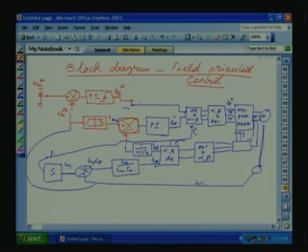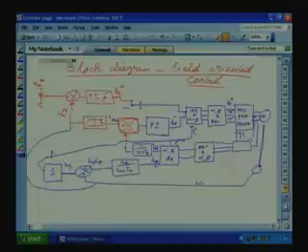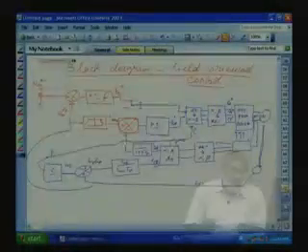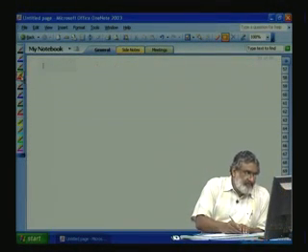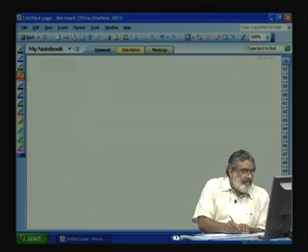Before the actual implementation is done. So this is the current hysteresis controller. Now if you want to use voltage control, how can it be done? See, we got the field oriented control now. Now how do you design your controller? For the separately excited DC machine, we have found a set of rules to find the PI controller. So let us draw the closed loop schematic. The same techniques we use for the separately excited DC motor, we can use here also. So let us see the closed loop controller block diagram. See, you have the omega reference.